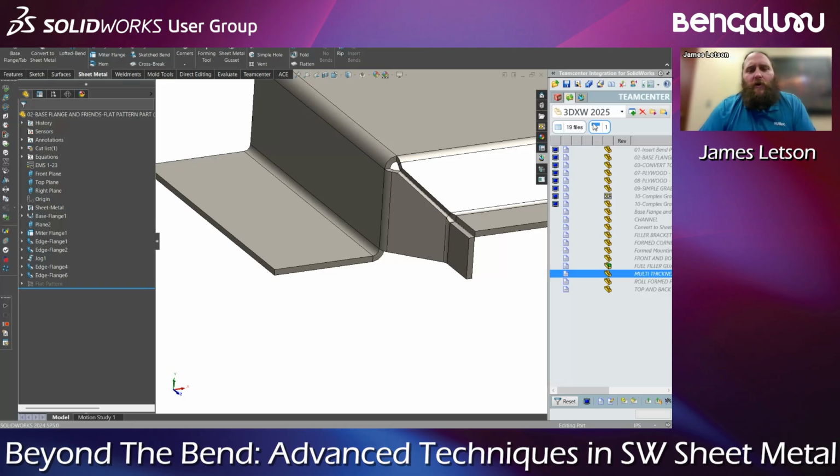So like I said, there is a universal rule in sheet metal, which is your bend radius should never be smaller than your material thickness. But really, the bend radius that you use for each material is going to be determined based on the fabrication shop's capabilities. If you're at a press brake, the tooling that press brake has will determine what your bend radius is ultimately.